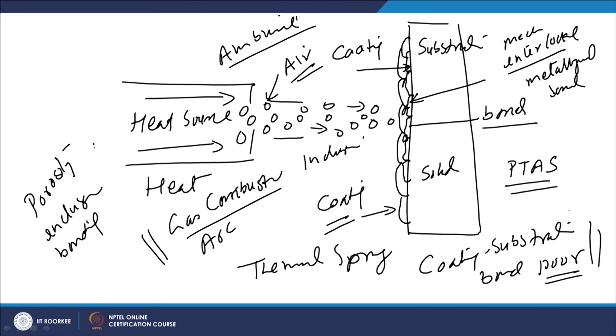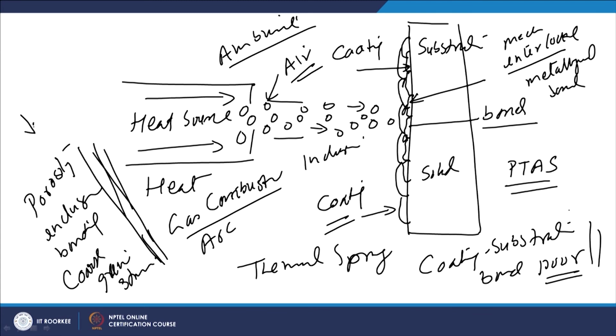These are the common problems, and if the cooling rate experienced by the material being deposited is very low, then we may get a very coarse grain structure as well, and these characteristics will lower the mechanical properties and reduce the tribological performance of such coatings.